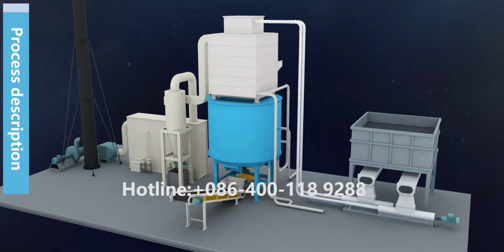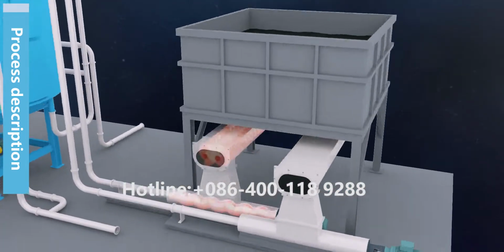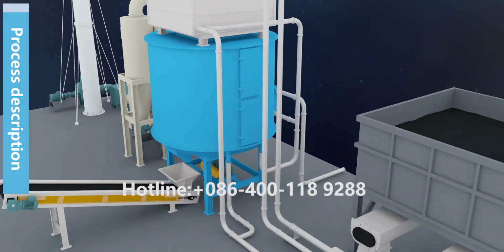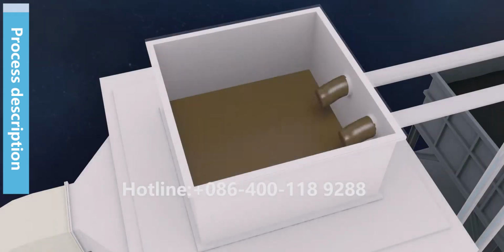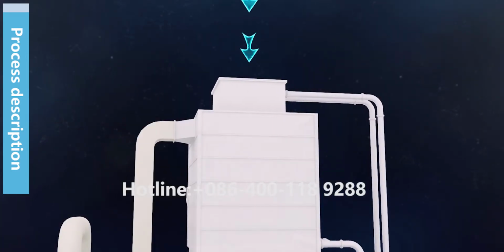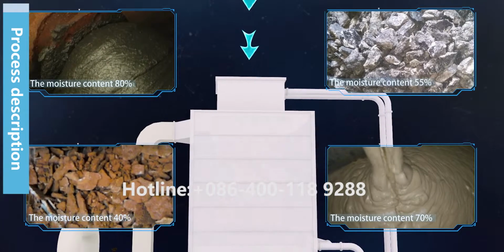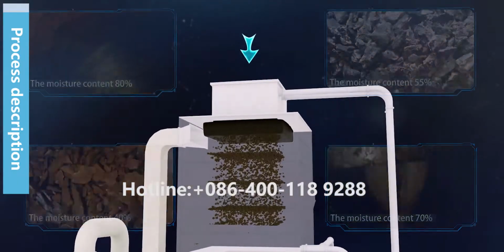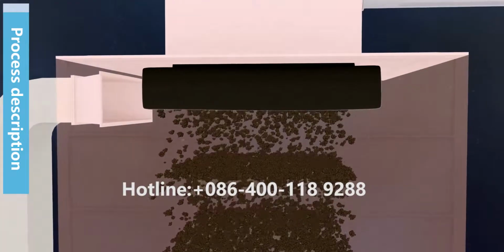The process introduction. The conveyor moves the sludge from the silo bottom into the granulator, which is heated by steam, drying the sludge. The granulator can granulate different kinds of sludge. During the granulation, the wet sludge moves down through the granulator, and the granulator makes the wet sludge into porous, non-sticky, high-specific-surface, popcorn-like particles.